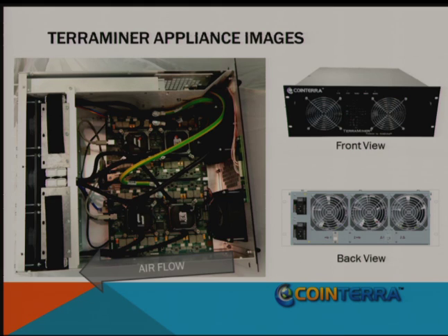Here is another picture of our TerraMiner appliance. 2 fans in the front pull air in, and 3 fans in the back push air out through the radiator. One thing to note is the thick car battery cables delivering 84 amps of current to each board at 12 volts.